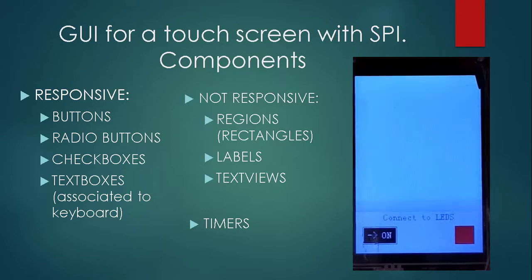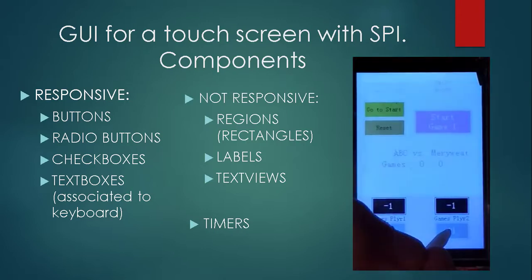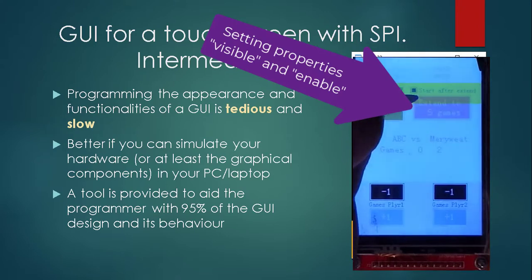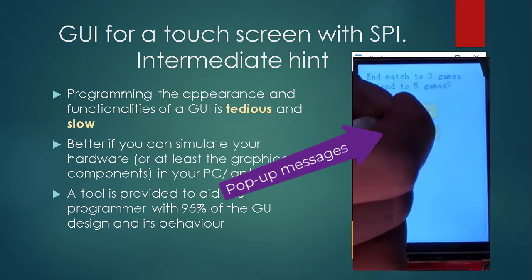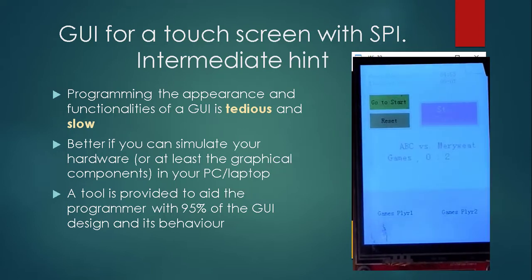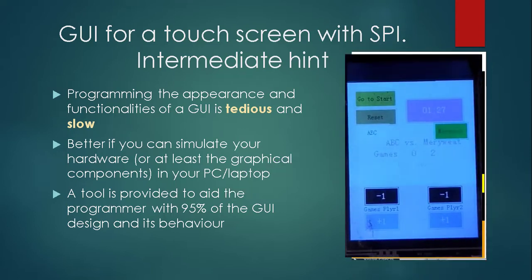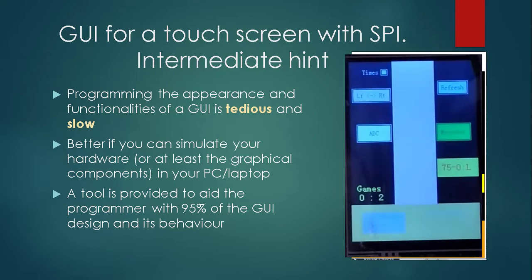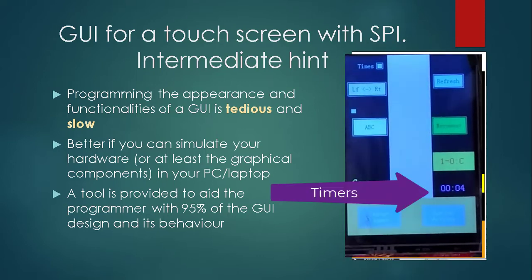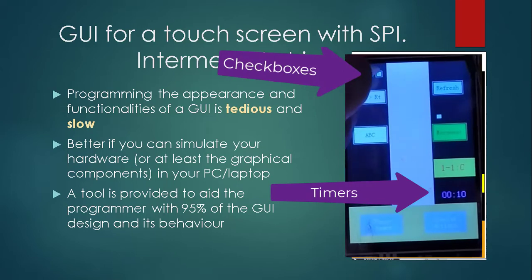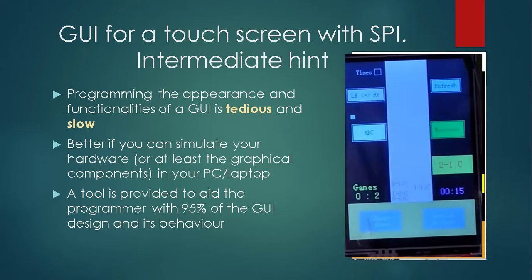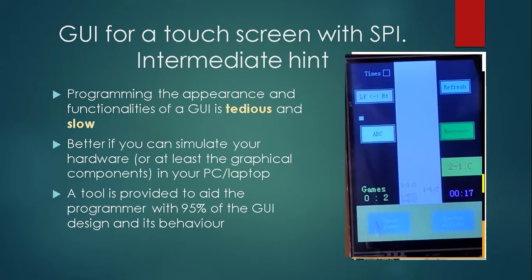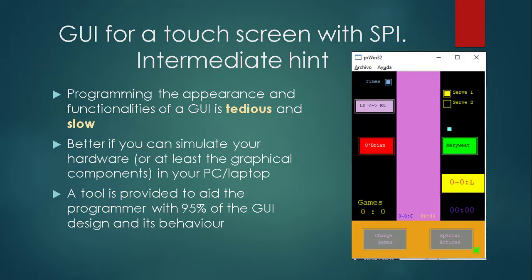However, if you plan to design your own and complete graphical interface, I must say that debugging the code is slow and requires the connection of the hardware. This is because you can do these steps in a more comfortable environment. So, in the second half of this video, you will learn how to open a Visual Studio project, or any similar that manages Win32 projects in C++, to develop 95% of the graphical interface and its functionalities. This is faster and does not require connecting any hardware. Once it is tested in your PC or laptop, you can complete your project with your microcontroller IDE.